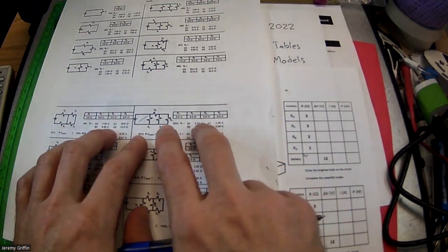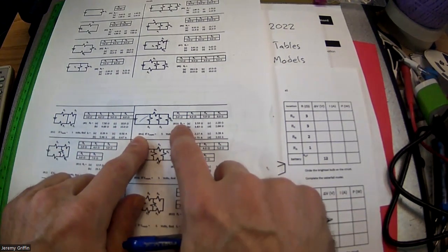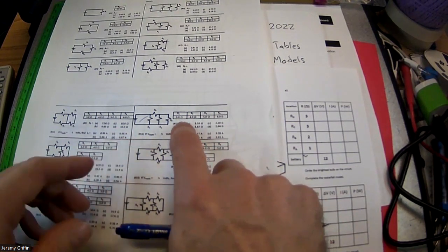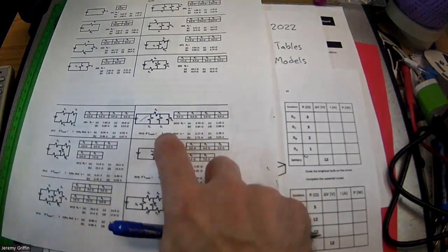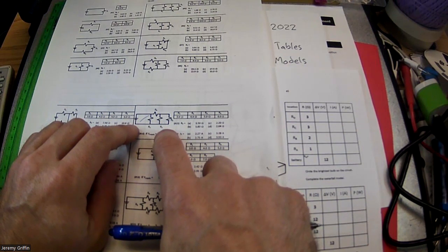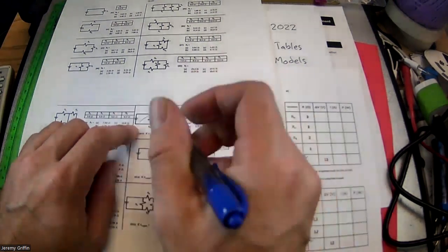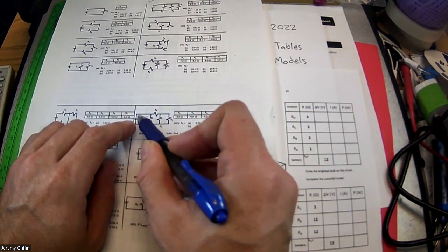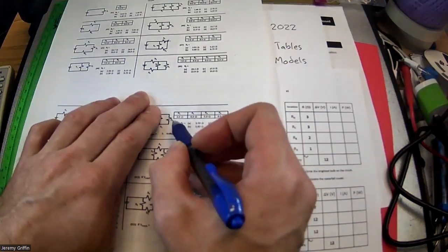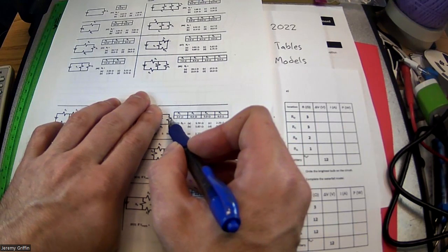Okay? But let's do one a bit more complex. Number 15, 16. You guys see a pair of questions here, 15, 16? Okay. So first question, equivalent resistance, and then the follow-up Ohm's law, but we'll worry about that later. Equivalent resistance. You guys remember yesterday I told you there's a process. We're going to find the voltage source, fly over to the opposite side of the circuit and then work our way back towards the source. So I'm looking at R3 right here, it's furthest away.